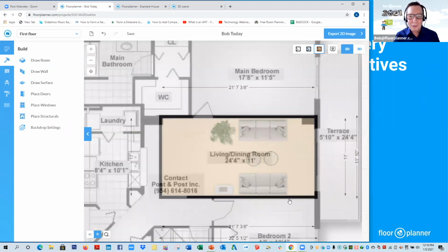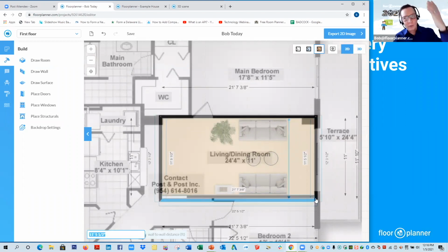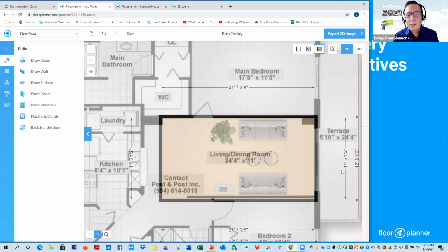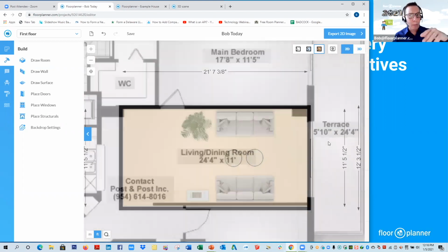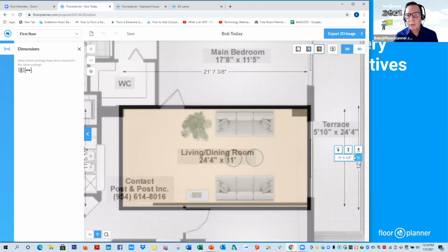Usually in this example, I have this wall just being a little bit different, so I'm going to fake this just a little bit and say, oh, it wasn't correctly 11 feet. If you need to make any of your dimensions exactly 11 feet, whether you have a background or not, you can just select a dimension line, sweep over top of it, and say, I want this to be exactly 11 feet. Don't hit enter. In these tabs up above, you have three options to edit the distance of your walls. The way you want to edit it, you have to select one of them. You can either edit it based on the wall above and bring it down, base it on the wall below and bring it up, or just go from the center. Of course, it's the wall below. We're going to go ahead and bring this up, so this is the click you need to do here.